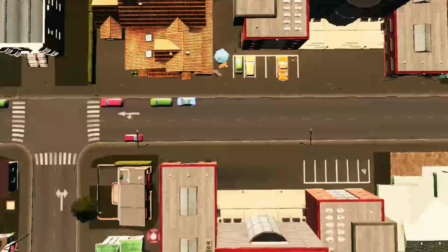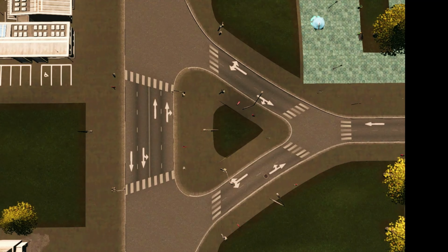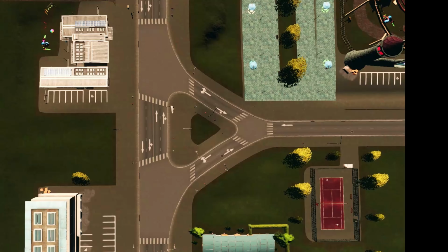At major highway intersections, engineers develop proper T-junctions using channelizing islands, lane separation, and controlled turning movements. These features help drivers slow down safely, identify priorities clearly, and enter highways smoothly. Simple village road connections, however, may only require basic link roads without large traffic islands. Good T-junction design provides better traffic control, reduced head-on collision risk, improved visibility, and safer turning operations.